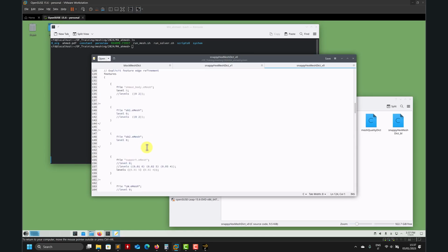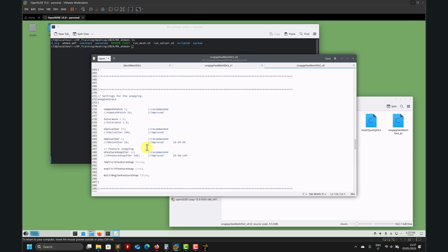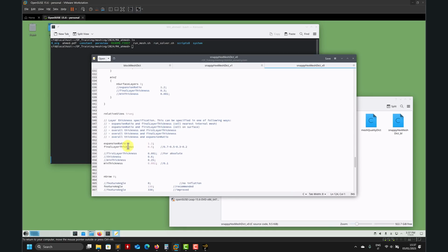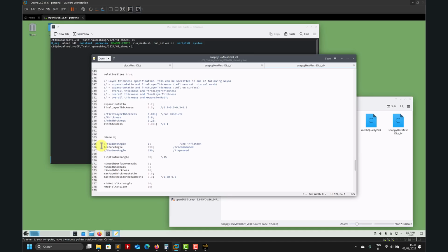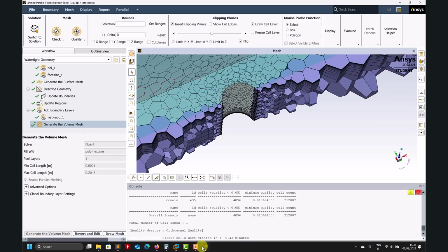And also I get two different values when it comes to meshing. There is one that boundary layer mentioned can have influence. Actually, there are two. This one I can have two, and the other one that I can have two is this one. I was modifying snappyHexMesh with a hammer, so if I have 10 surfaces, I should be able to put 10. I just did it for two, but in any case, just testing a concept, it worked. But yeah, just to mention that.